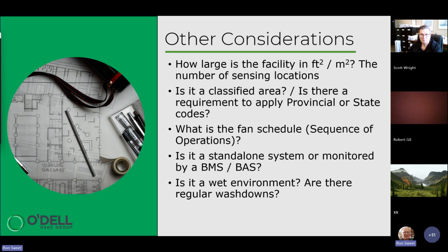Fire station. During the winter months, with the inclement weather, they're going to be washing down those fire vehicles inside the firehouse. They're going to be spraying water all over the place. But at the same time, you've got CO and NO2 sensors in there that are monitoring the facility for buildup of vehicle exhaust. Knowing that you're going to be installing those devices into a firehouse, they can be provided with waterproof housings and splash guards that protect the sensor elements, because we all know that electronics and water don't play nice together.